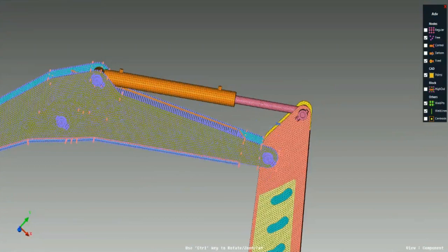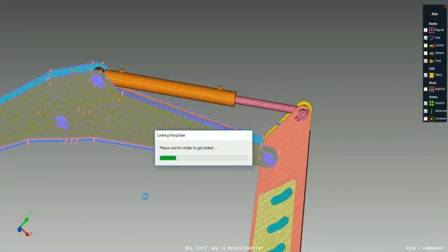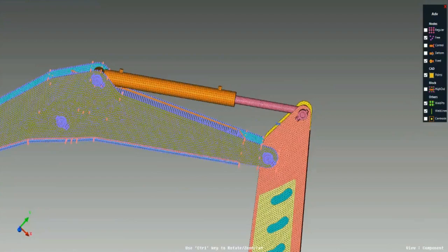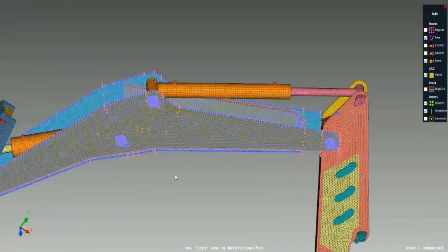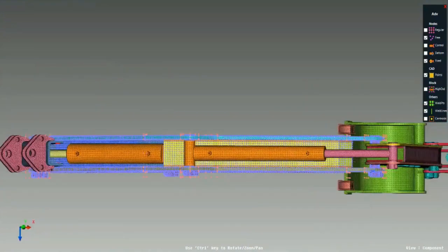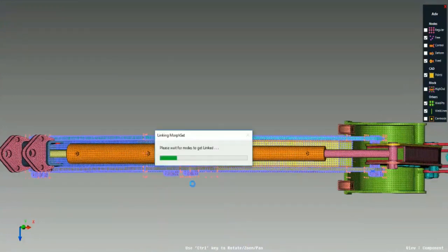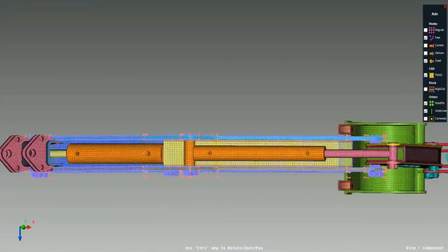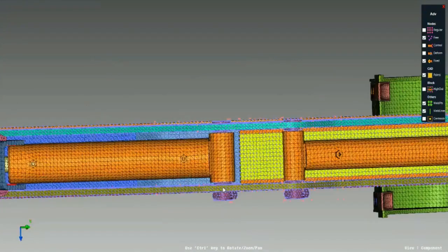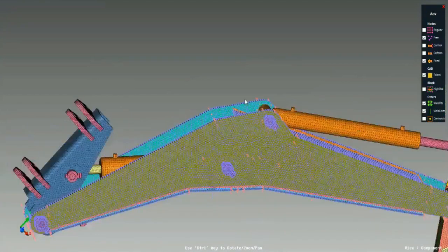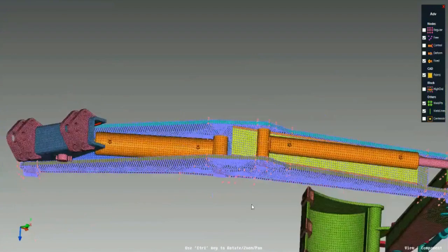All these changes have been done using the control block morphing technique. Now we can vary the width of this entire boom section on either side. Individually we can have control, or we can just create one parameter to change the width on either side, on the baseline boom model, to get a completely new design within very little time.